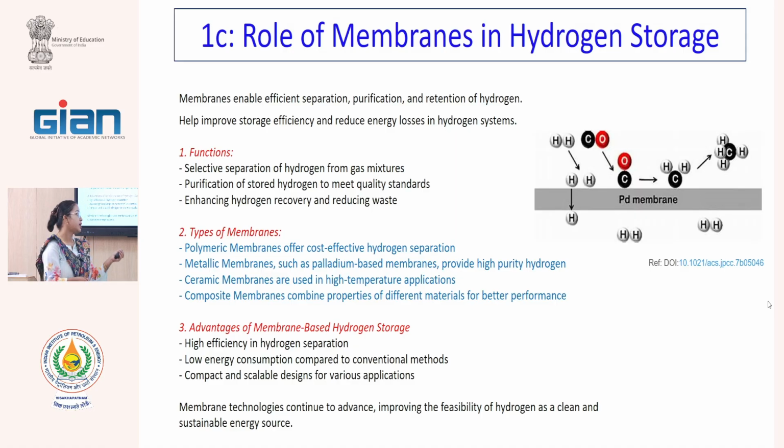What are the typical conditions when we are having this kind of polymeric membrane? We can have it exposed to a vacuum. Vacuum will do the evaporation of solvent very fast, and also we can do this evaporation of solvent in an inert atmosphere.